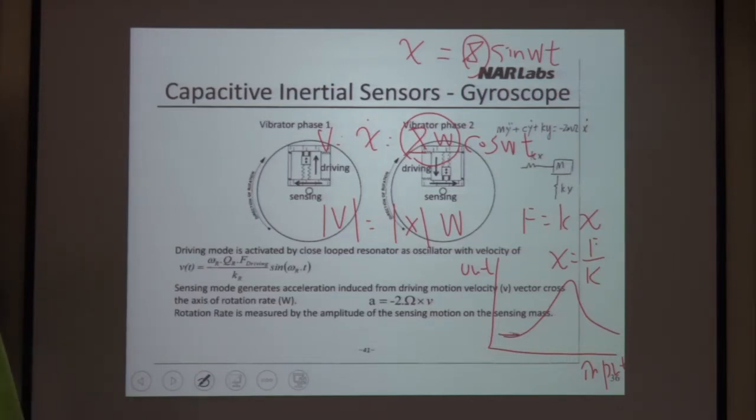So at low frequency, this is frequency, and output divided by input. This is transfer function T. Transfer function, output divided by input. Y coordinate, X coordinate is the frequency omega. So at low frequency, this is 1. But at resonance frequency, the magnitude is quality factor Q times 1.